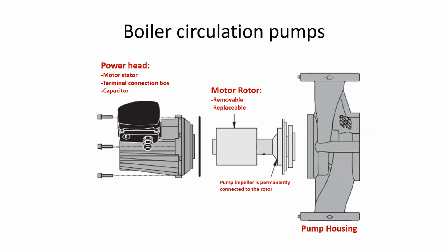There's something called the power head, which is the motor stator, the terminal connection box, and the capacitor. There is then the motor rotor, which is removable and replaceable and permanently connected to the pump impeller. And then there is the pump housing. All three of these items can be replaced independently and are intended to be replaced as their serviceable life reaches